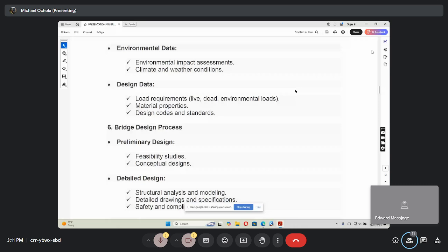You have seen the load path and the configuration. For you to sit a day, or half a day, or 2-3 days, and model your bridge. Once you model a bridge, you are able to put the boundary conditions. Also from structures, you must know. And then from there, you run analysis and do your design. From design, you do detailing. You need to have knowledge of AutoCAD and Revit Structure for detailing. It's very important. Then the specification comes in, the safety and compliance check come in, and you're able to generate a report. So there are so many things you do at design stage.